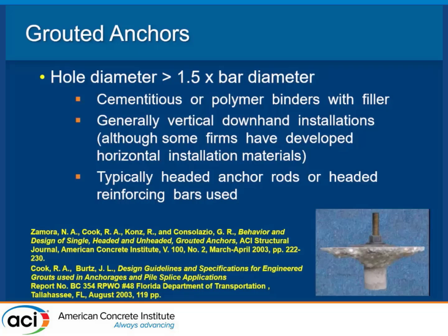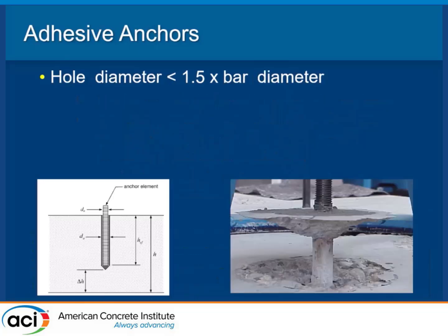You will find some directions out there on how to use a grouted anchor if that is something that you're really interested in. Adhesive anchors we do cover, and they have a little bit tighter hole, largely to save a little bit on the epoxy. And the biggest problem we generally have with adhesive anchors is we get a bond failure. And once again, the biggest problem with why we get bond failures is the hole. We didn't clean out the hole properly. We didn't do what the manufacturer told us to do.